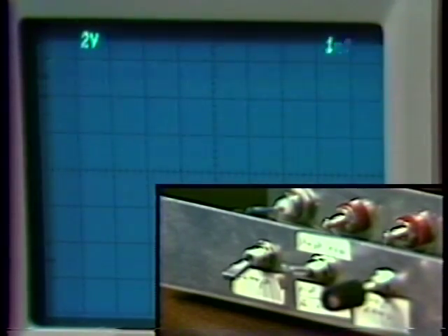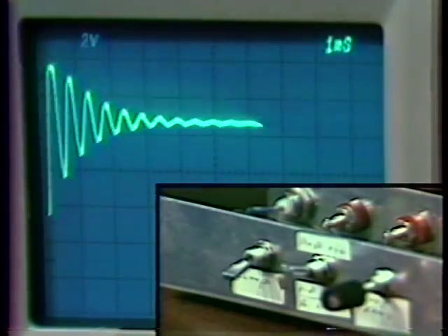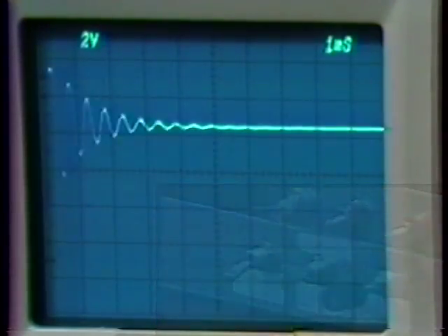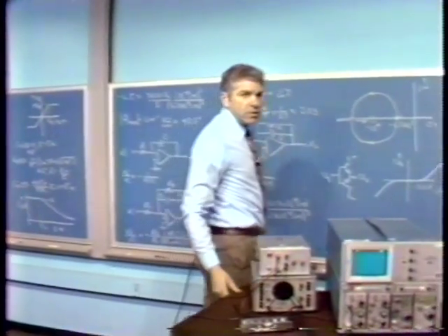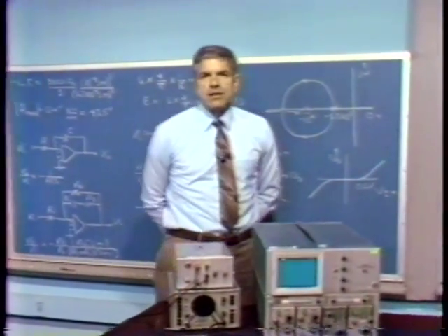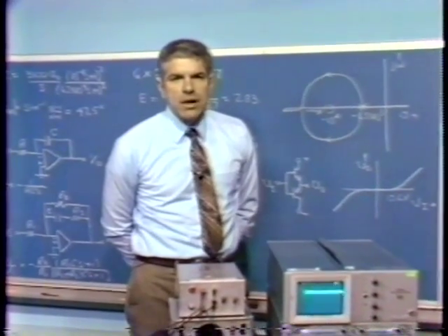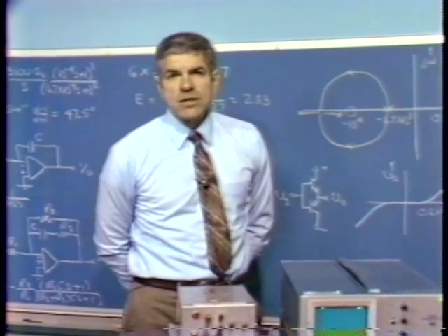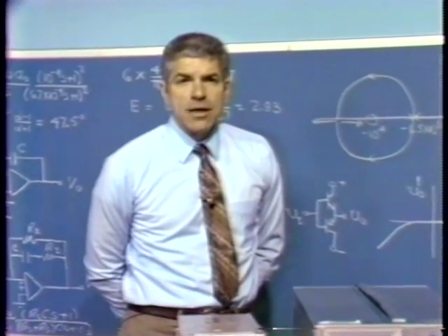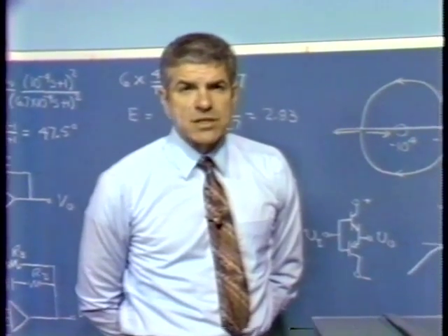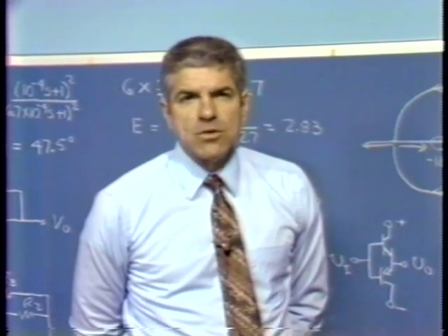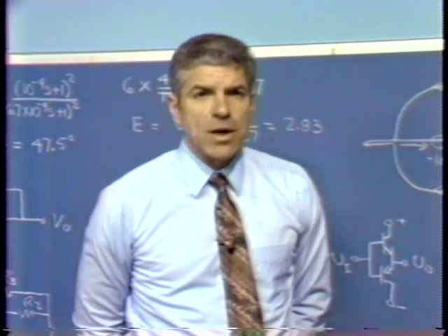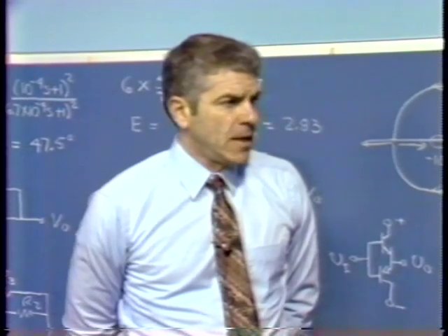So we've found quite an effective way to really exploit the characteristics or the behavior of this particular nonlinear system. What we do, and there's certainly no generality in nonlinear compensation, is look for a point in the loop where signal levels change rather dramatically when the system starts to oscillate, and see if we can somehow use that information to improve the performance. We found a rather easy way to do it in this particular case.